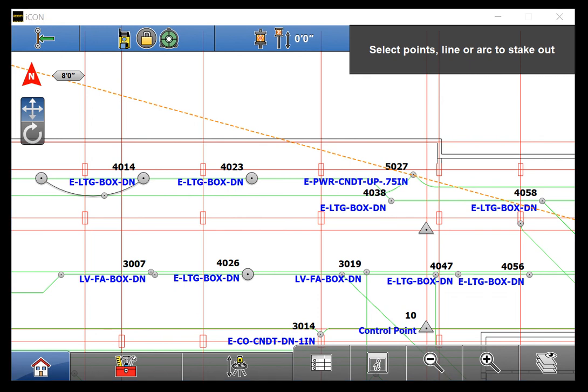As you can see, the program Layout Lines has so many useful applications that I won't even try to cover them all in one video. Just a couple popular uses are checking control lines after initially setting up your total station to make sure you are correctly oriented to the building, extending your own control lines to tape measure from later, laying out electrical room walls so someone else can lay out the electrical room with a tape measure while you are busy laying out in another area, and laying out underground conduit for excavations.